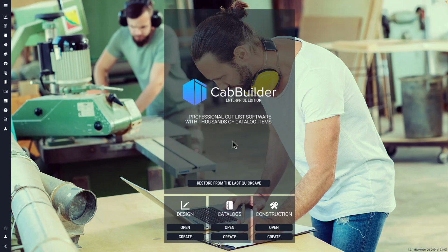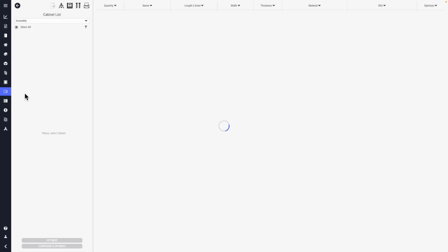In the next few videos, we'll focus on how we can create our standard cutout, drill, and pocket tool bits, how we can set them up within our tool sets, and extract our G-codes. Now, tool bits are going to be defined in the tool library, which can be found in the cut list. So we head on over to that module, and the tool library will be found at the top left of